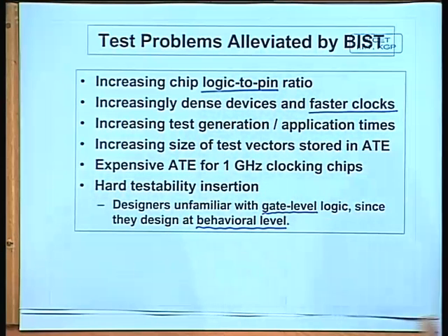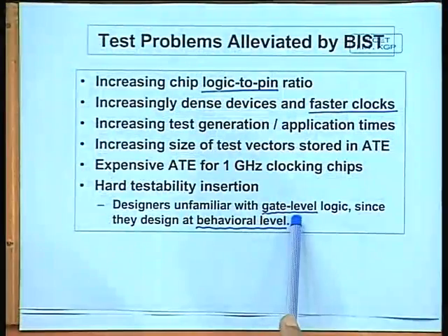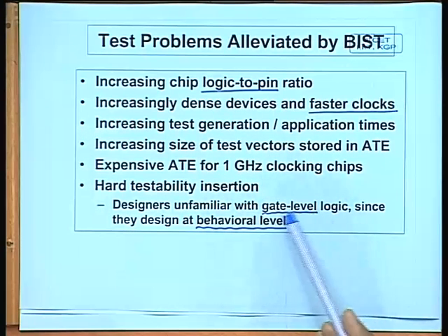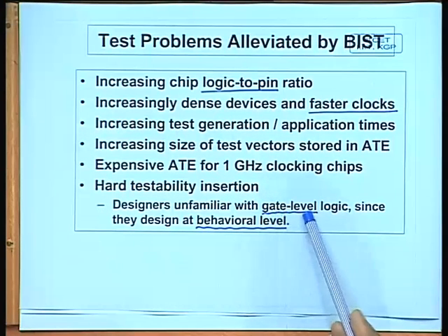The designer may not be very familiar with the gate level logic which the synthesizer has synthesized, because after optimization it is typically very difficult to identify the gate level logic components and correlate them with the higher level behavioral components.